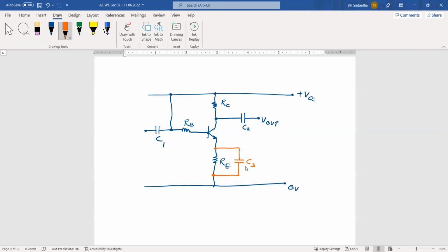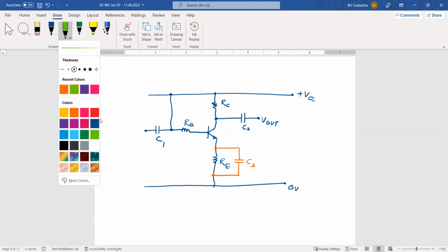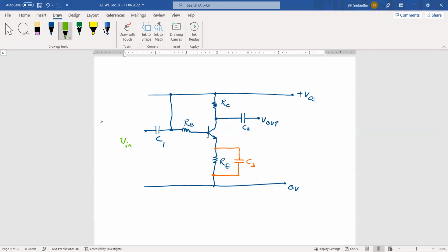You can see here that when we write the equation for this AC component, do you remember the previous one? We wrote this one. When we give this AC voltage V in here, and we had this IB, that is AC component, and this IC, and this one IE. We put this IE because that RE resistor is there. Because of this resistor, that effect is also there for this AC value. For example, we wrote this equation 0 equals IC RC plus VCE, and then IE RE.